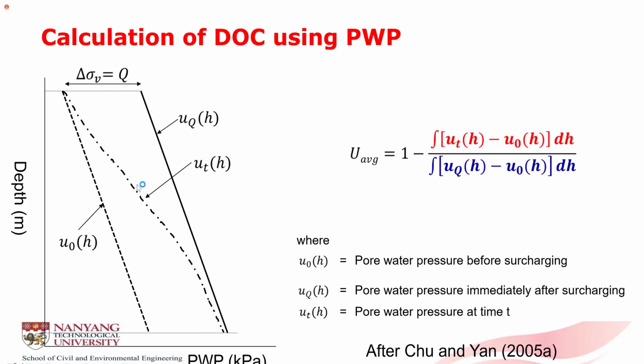If it's for land reclamation, the load is applied over a larger extent, so the 100 kPa increase in pore pressure should be everywhere. If you have single drainage, let's say you wait for half a year, then the pore pressure will dissipate from the initial pore pressure line to the line over here.